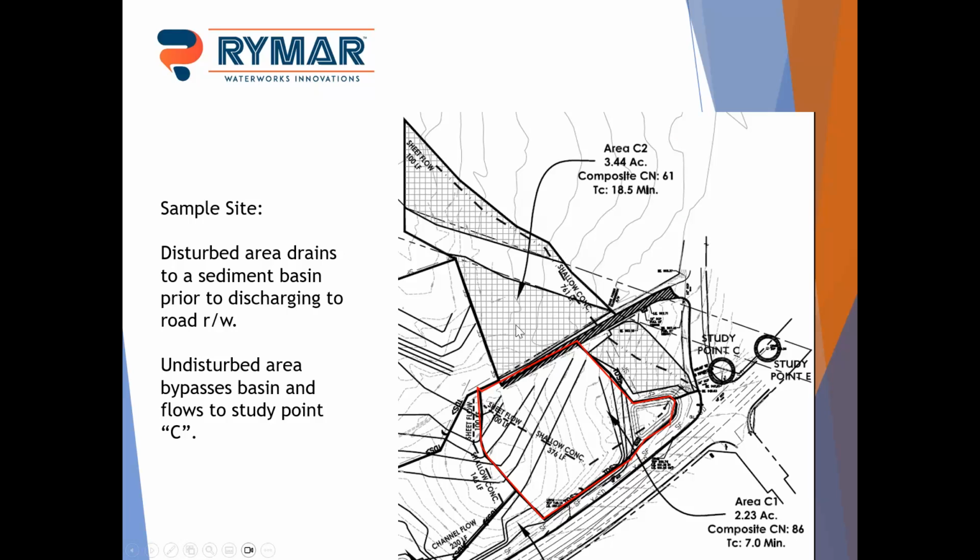It's about a 5.25 acre site. There's about 3.4 acres here that was not being developed. There's about 2.25 acres here that was being developed. We're putting in a sediment basin in this corner, which is also acting as a detention pond. So the disturbed area drains to the basin.